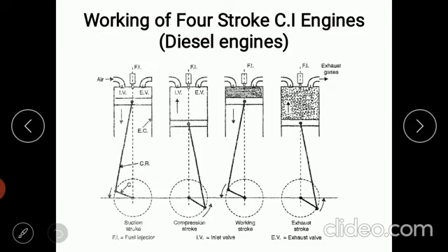But in case of combustion in SI engine, it is just like burning a piece of paper from one end to another end. So that is gradual. Here the combustion is erratic. That's why compared to SI engine, CI engine will produce more noise, because the combustion is relying on auto ignition of the air fuel mixture. During expansion stroke or combustion stroke also, both inlet valve and exhaust valve are kept in a closed condition.